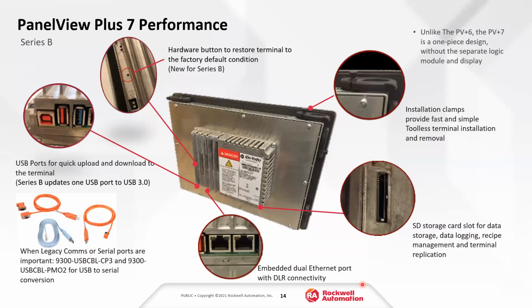Now, for those who are familiar with the PanelView Plus 6, one of the other big changes when we move from the 6 to the 7 is that there was a Logix module that you would put onto the back of a PanelView Plus 6 that was replaceable. In this case, the PanelView Plus 7 is a one-piece design. So they do show this on the back here, but there is no Logix module you have to go out and purchase. Therefore, if the screen on the 7 failed, you would have to send the whole unit back in for repair. An SD card slot is also available.